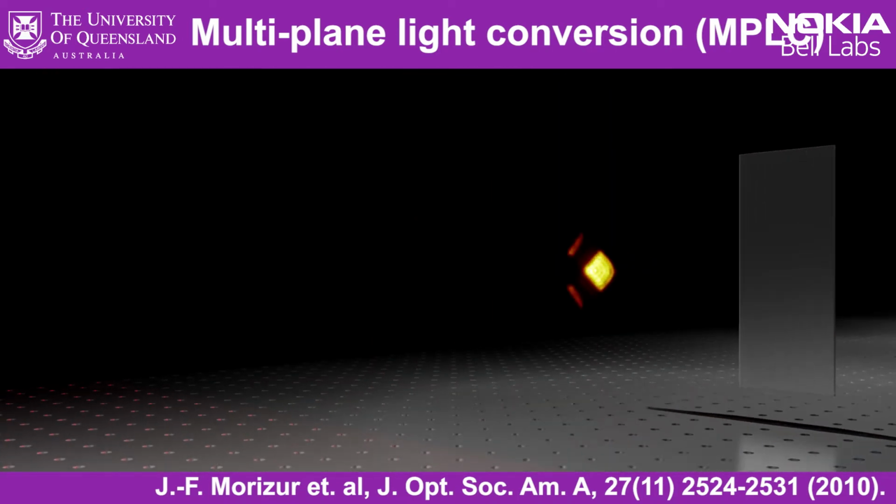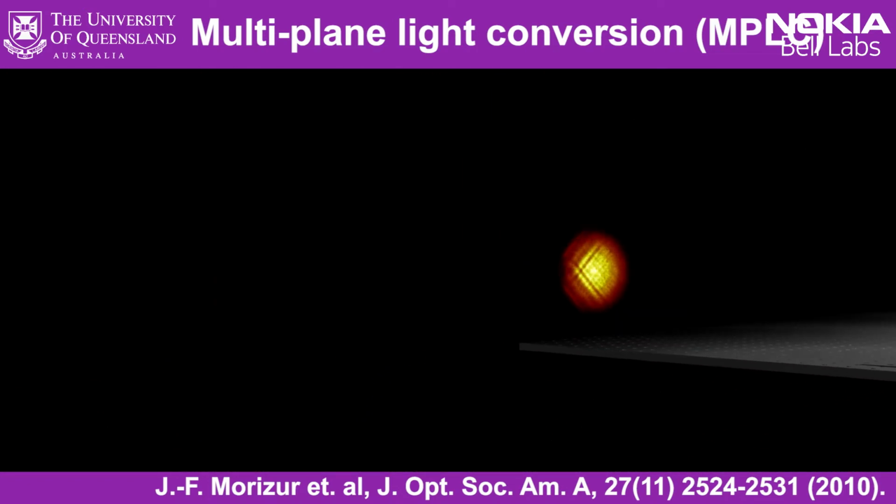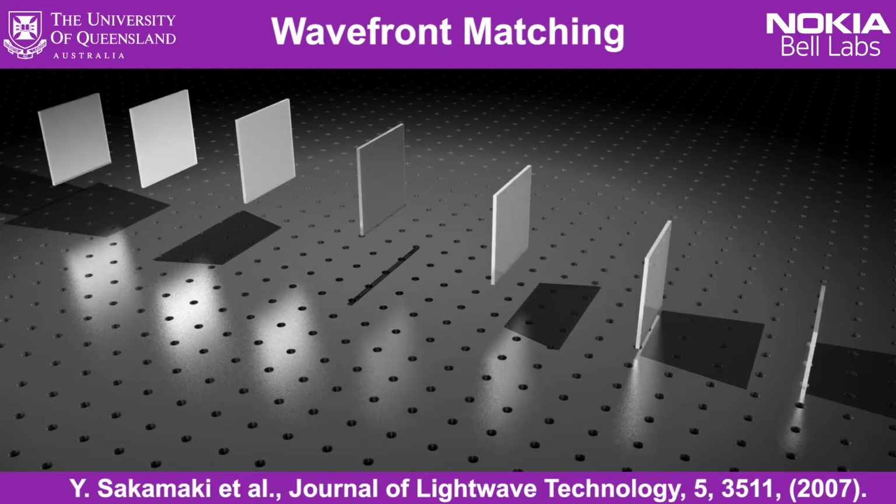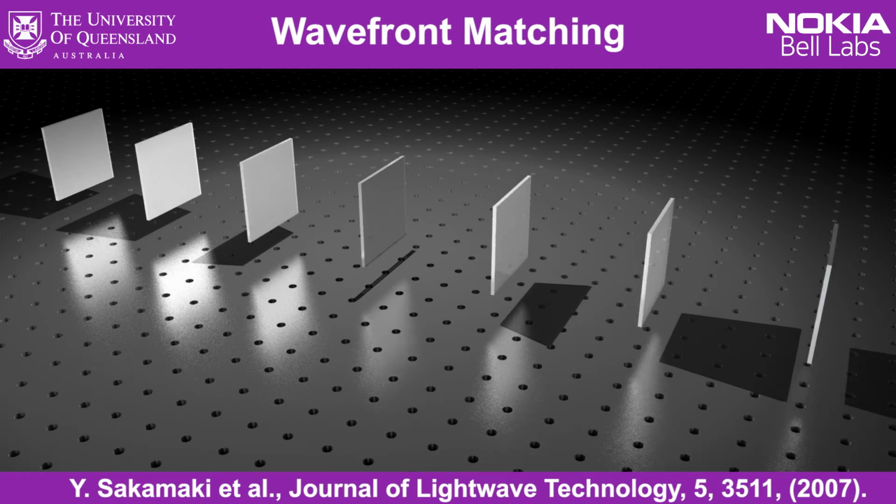Like the photonic lantern, this device is also just phase manipulation, so it's lossless, but it's capable of more easily implementing arbitrary transformations, as it's not constrained by the same limitations of what you can actually manufacture as a tapered fiber device, right, like the photonic lantern is. Calculating the phase masks required to implement this conversion can be done by using the masks to match the phases of the input and output mode sets at each plane. So ultimately, if we want this device to actually work, we need the modes in one direction to match the modes in the opposite direction. They need to be the same.